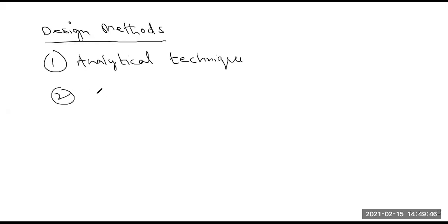So just like for the previous impedance matching network that we covered in our previous lecture, that is the L network, there are two possibilities. You can either design your circuit using equations. Okay, so there are two possibilities. We can design our single stub using an analytical technique, and as before, we have an option of using the Smith chart technique.